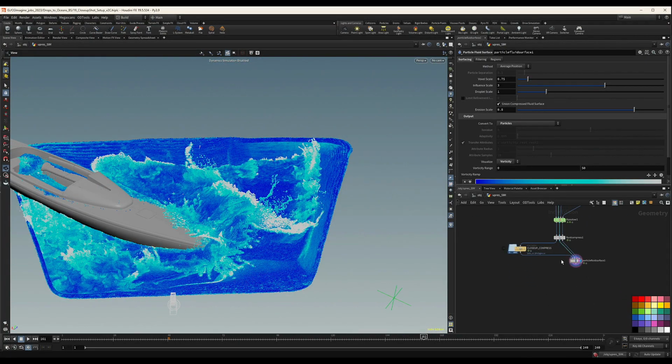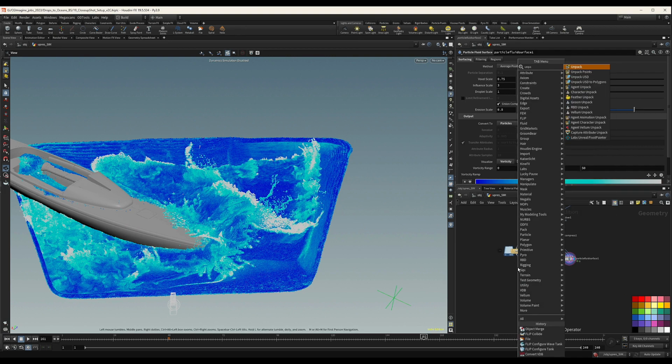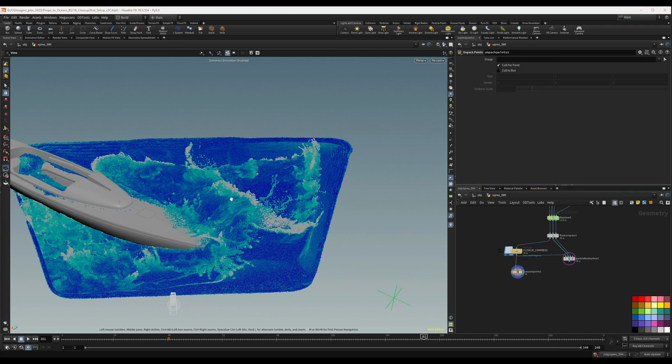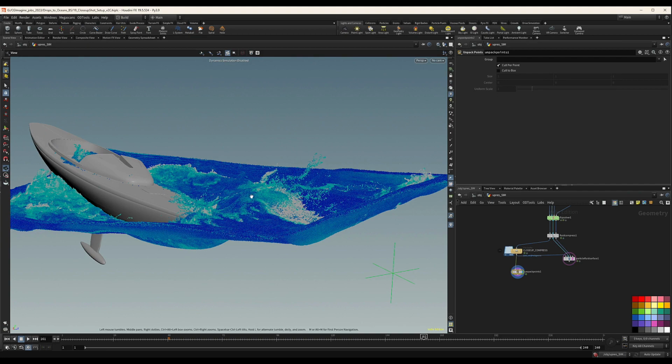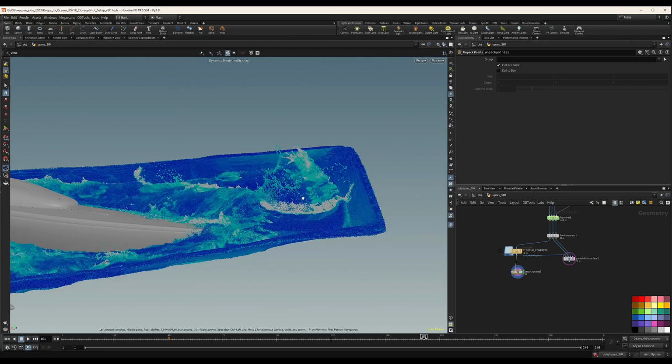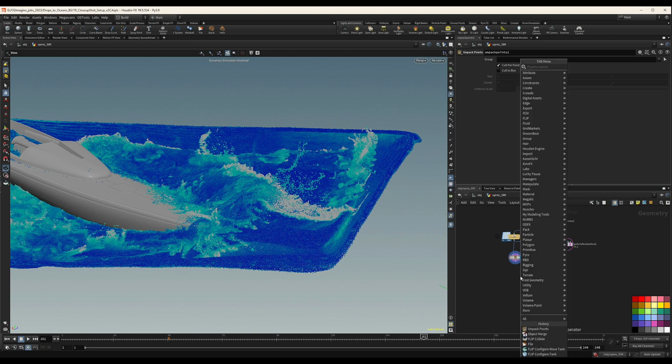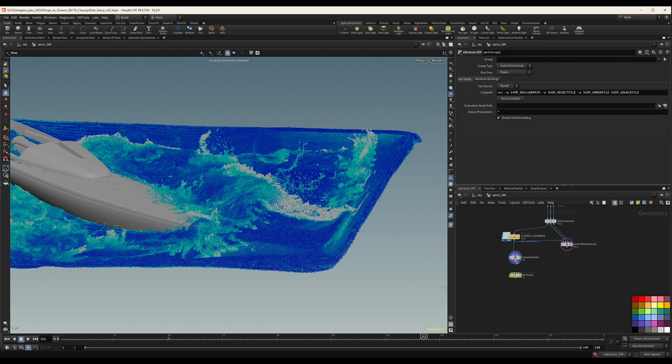So let's start. I want to start meshing this. To start meshing, let's first do unpack points. I want to set the P scale based on the velocities. We could do that based on vortices, but I want the particles that are shooting fast to have a smaller P scale. So let's do that. No, sorry, it's a point VOP. P scale by V.